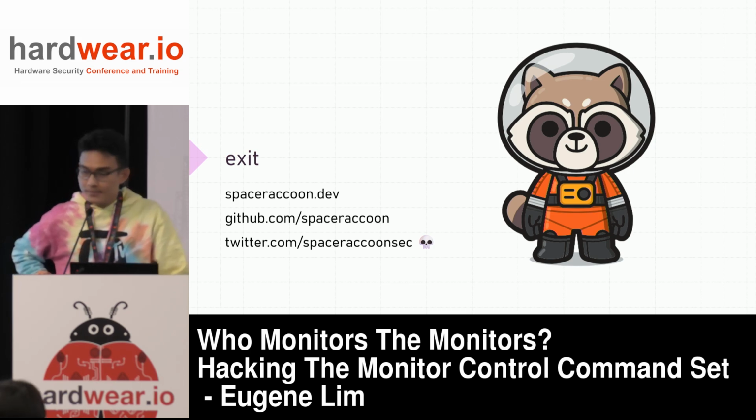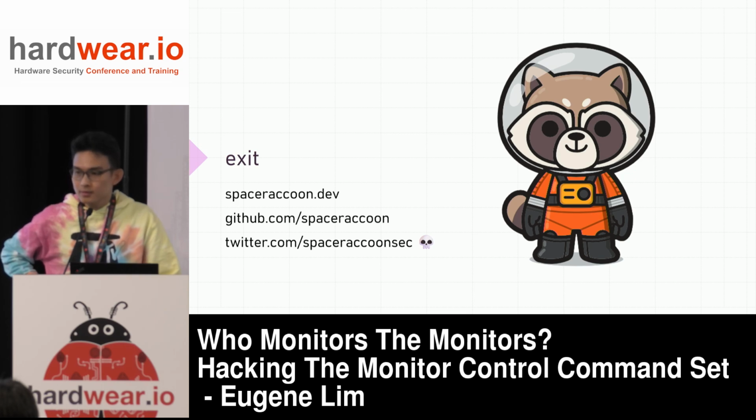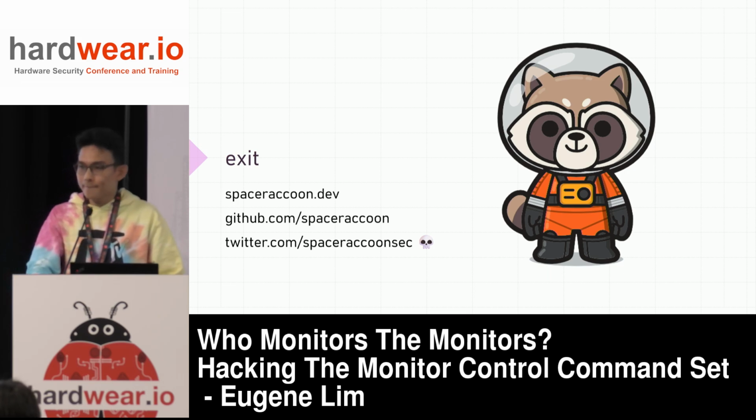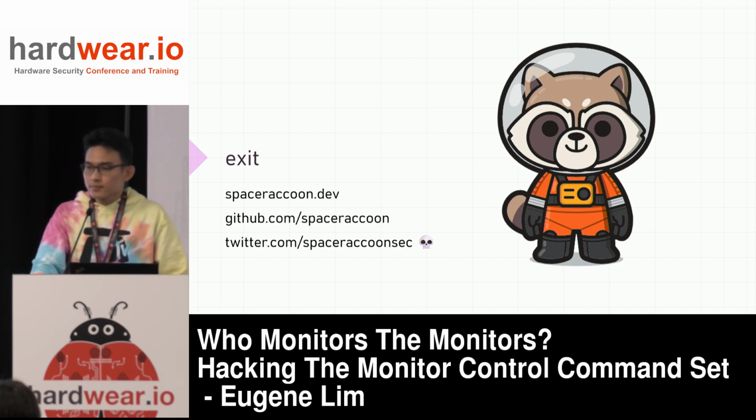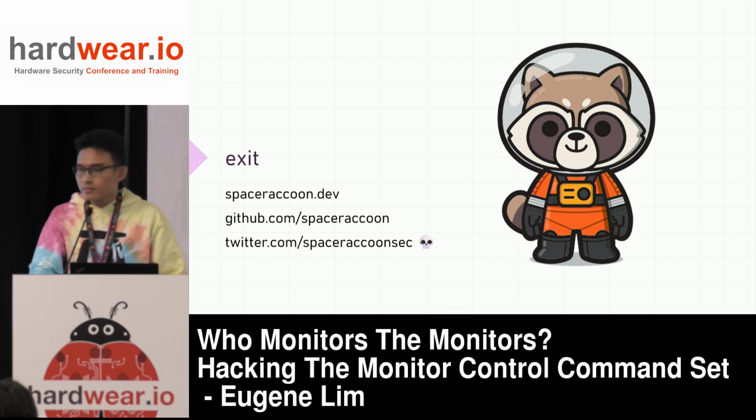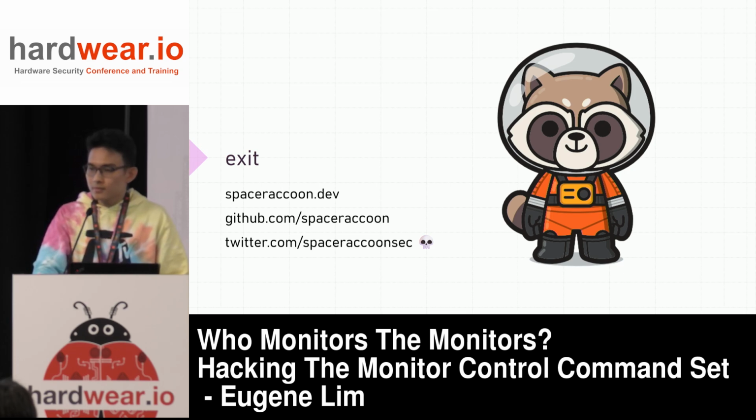Okay, I was more interested in whether you had looked at different monitors than have been looked at thus far. And on your example of host to monitor exploitation, I believe you were looking at a read serial number opcode. You said there was a sanity check in there, like check for 5 or something like that, but I wasn't clear since you went through it quickly. Were you saying that that particular opcode could still read arbitrary memory and therefore be used to dump the entire memory? And if so, is there a separation of the memory between display data and the code? Could you dump the firmware that way instead of having to do as much reverse engineering?